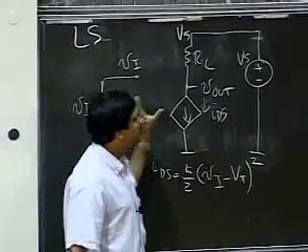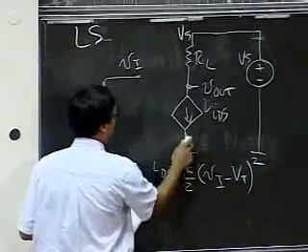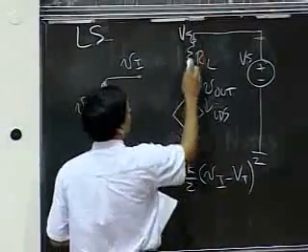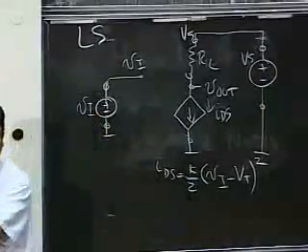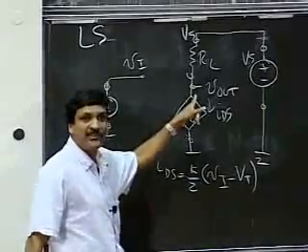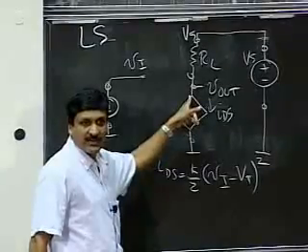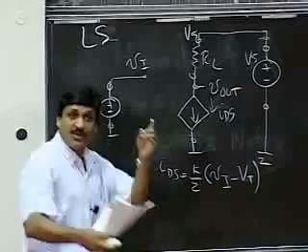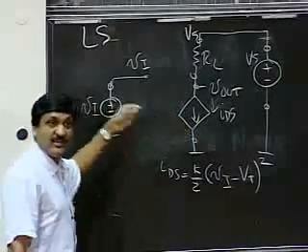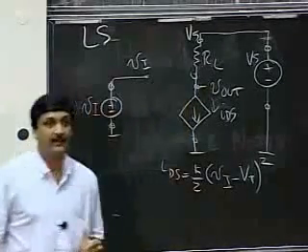And what I'm going to do is keep the same circuit, keep the same circuit connections, and simply pull out the large signal model for the element and replace it with the small signal element model. And by their nature, the small signal models are all going to be linear. So what I'm going to be left with is a linear circuit with simple linear circuit elements in there.